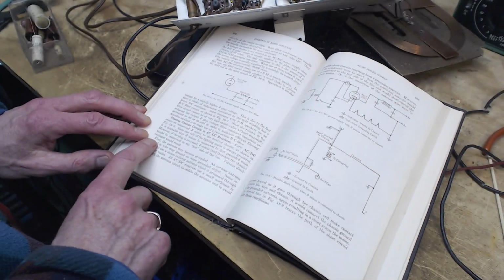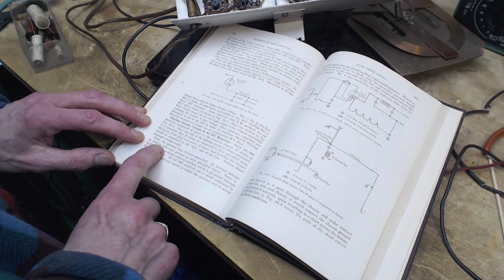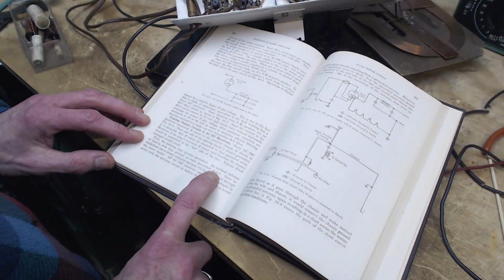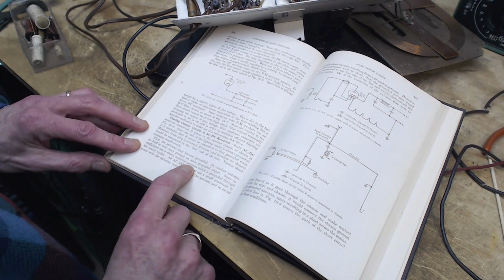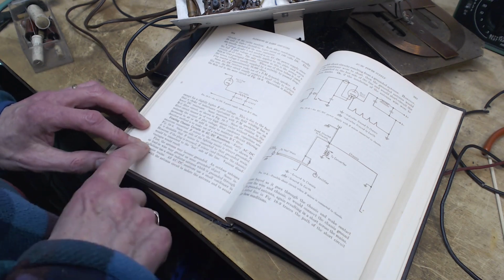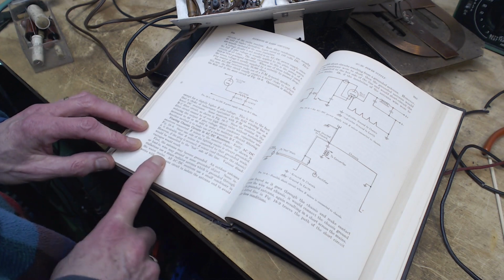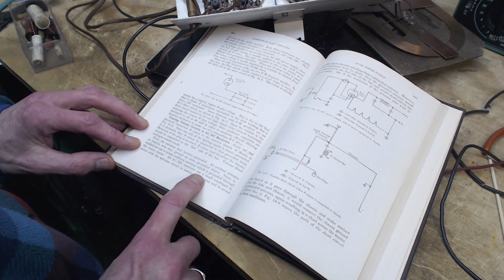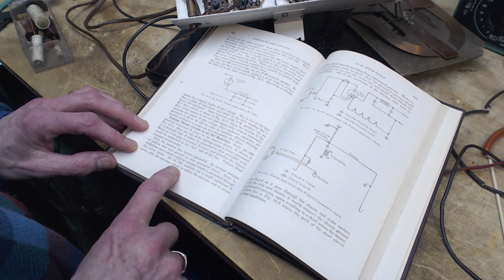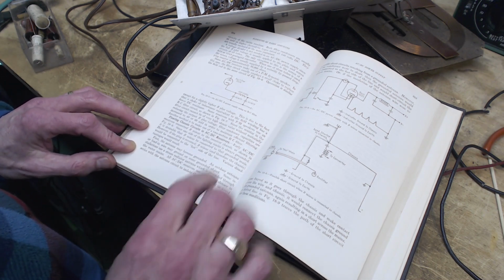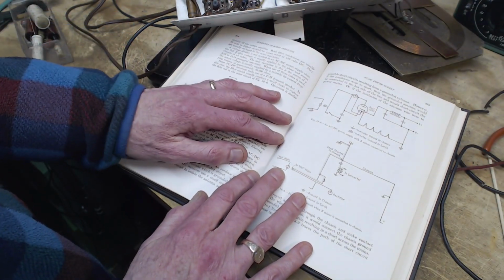Floating the chassis. First, the antenna may become grounded. An outdoor antenna or lead-in wire may ground on some grounded object. Some installations use a steam radiator antenna. I don't know how many people have steam radiators in their houses anymore, but steam radiator antenna, which is grounded through the water mains. All AC/DC receivers use a small condenser, capacitor, in series with the antenna circuit to isolate the antenna and to avoid the possible short circuits resulting from a grounded antenna.